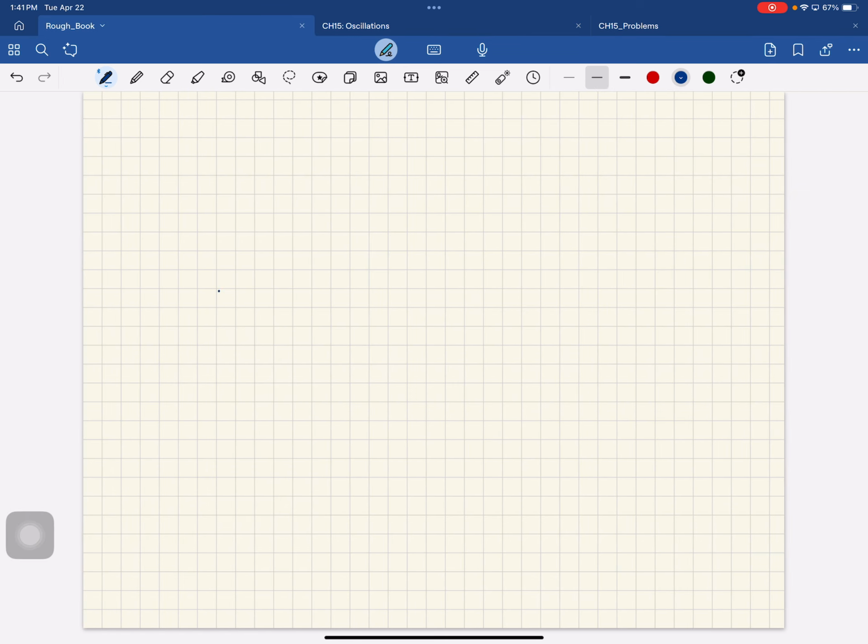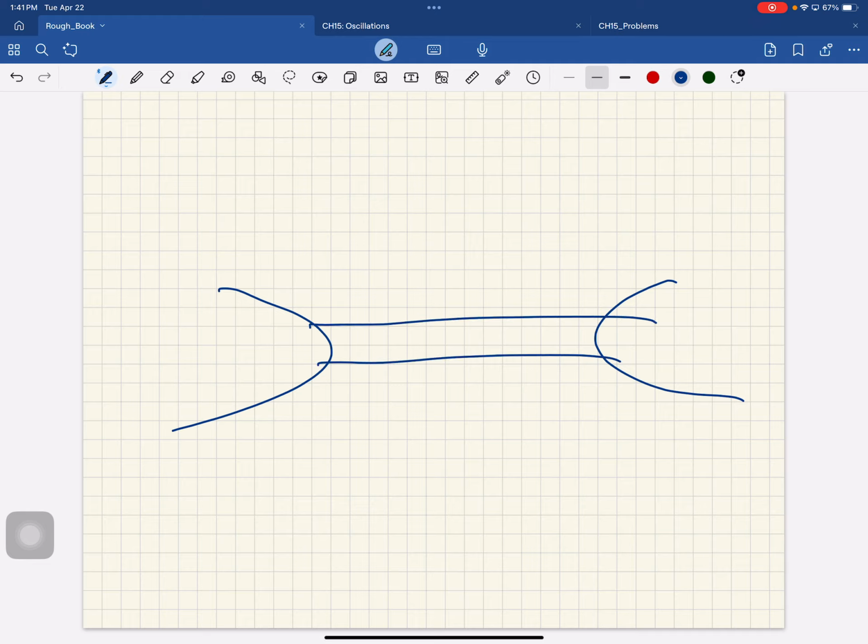This bridge was built somewhere near Seattle. This is a top view. There's the bridge, and there are the piers under the bridge, and the wind was blowing, and vortices would develop, and these vortices would break away at a frequency, let's say 10 times every 2 seconds or whatever. That frequency matched a natural frequency of this bridge. So it's like you're applying a force that matched the natural frequency of the bridge. And here's what happened.